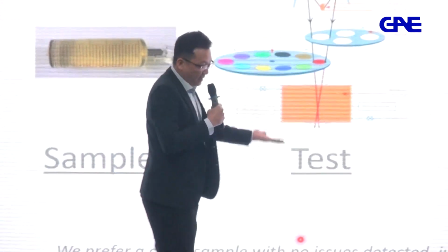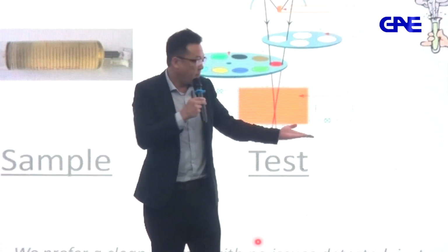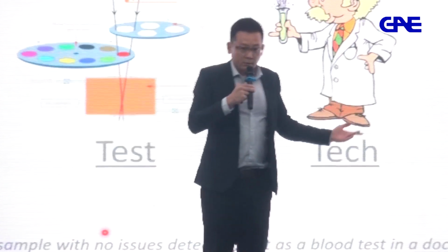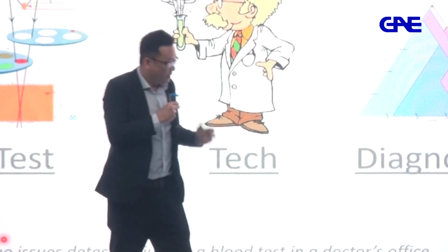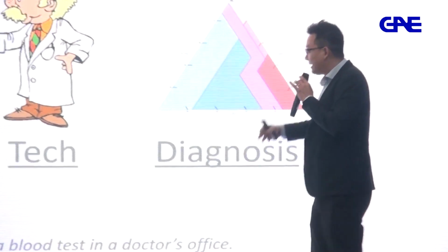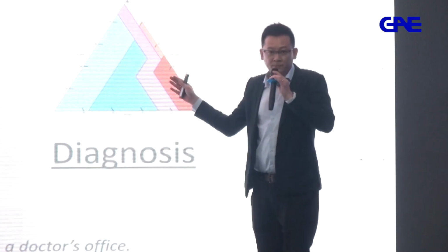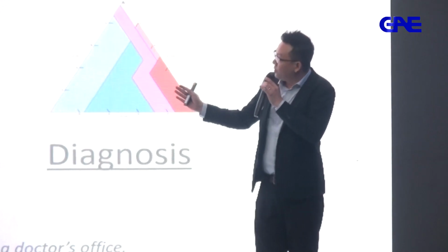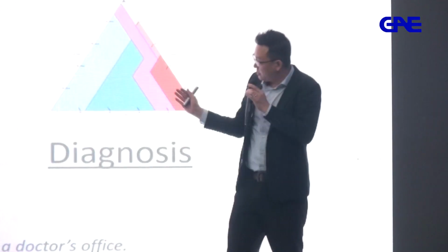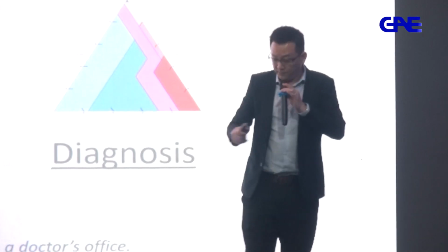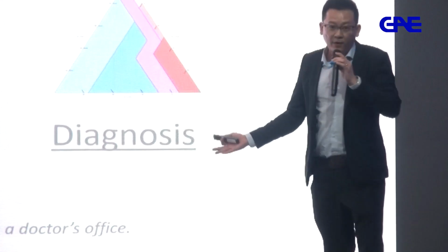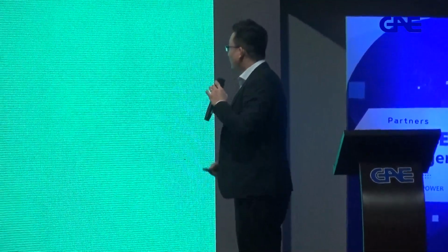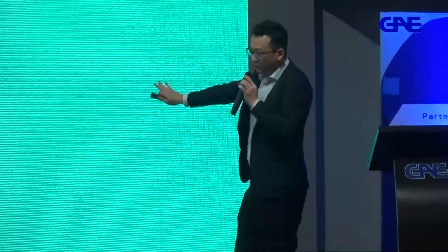All right. So from there, the technician, field service engineer, the product subject matter expert comes up representing the doctor. We'll talk about the technology. Then from there, we diagnose and analyze from this. Okay, I believe most of you should be very familiar with the diagnostic. This is the Duval triangle. Okay, so from there, we identify what exactly is wrong with the transformer. All right, so next topic. Before we go to the next topic, any question with DGA?